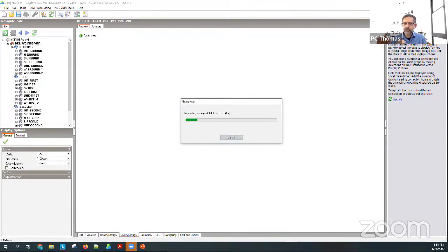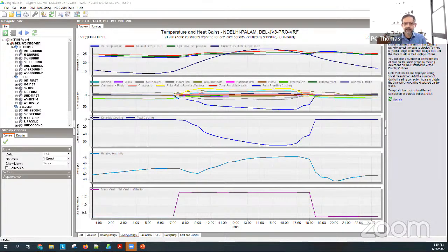So if you are not able to reduce the heat load below a particular standard size of chillers, and if you have more than one chiller, then you can make up combinations of chillers, then the costing becomes difficult, or the cost saving becomes a bit difficult, right?